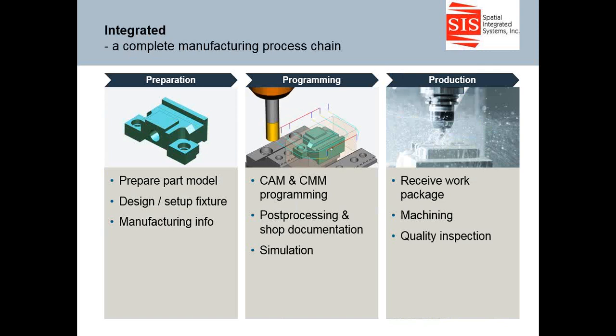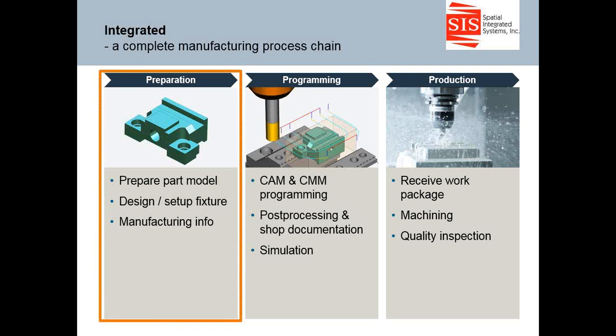Now, in integrated, there are three main steps that comprise the integrated process overall with CAD, CAM, and CNC. It starts with the part design data. NX provides advanced 3D CAD software not only to prepare the part model for NC programming, but also to design the associative fixtures. The entire machining setup can also be created by using a powerful assembly capability in NX.